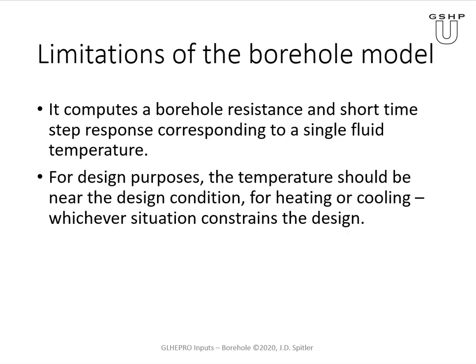And borehole resistance can change significantly between heating and cooling, particularly if in cooling mode the flow drops into laminar flow. So if you have a water antifreeze mixture, usually the viscosity increases as the temperature gets lower. And that can mean in some cases that you drop from turbulent flow into laminar flow and the borehole resistance goes up. So it's something that needs to be considered.